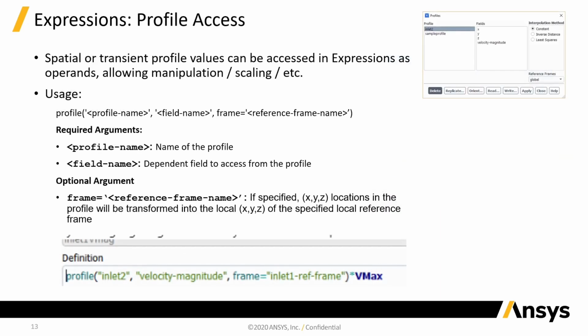Another feature which is bringing the power of these expressions to the fore is the fact you can now work with profiles under expressions, something you've been able to do in CFX for a long time. So what that means is that you can use expressions to do transformations of profile data, etc., and bring it in. So it gives you a lot more flexibility with profiles.